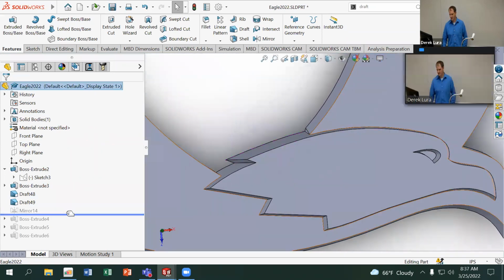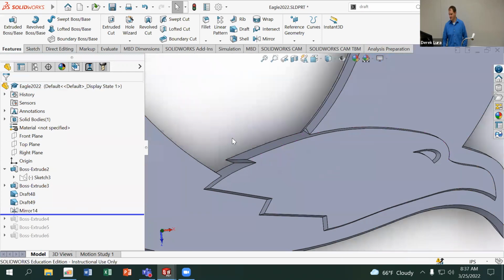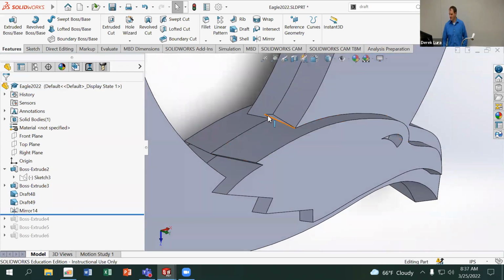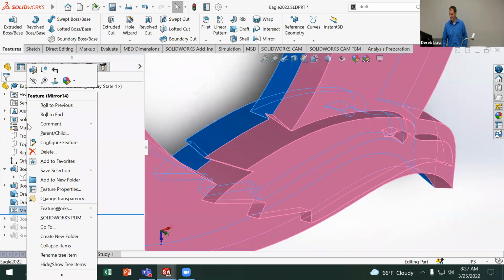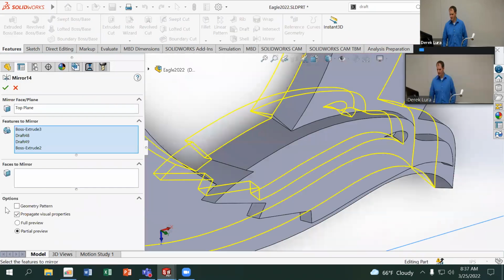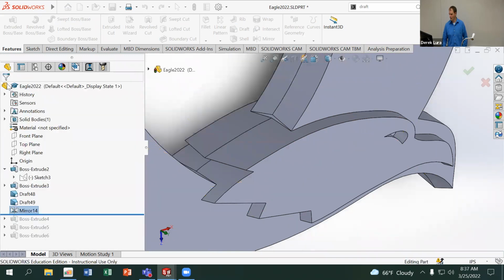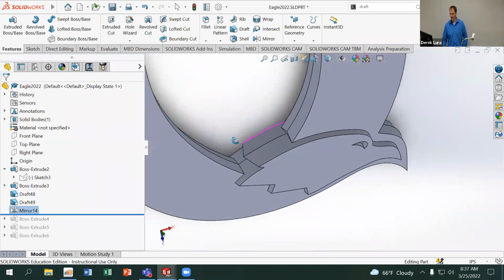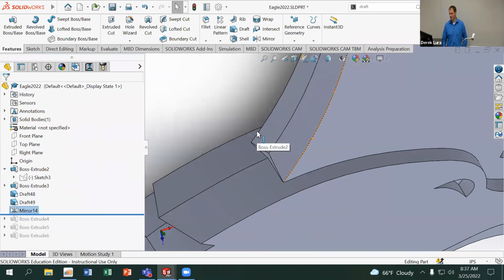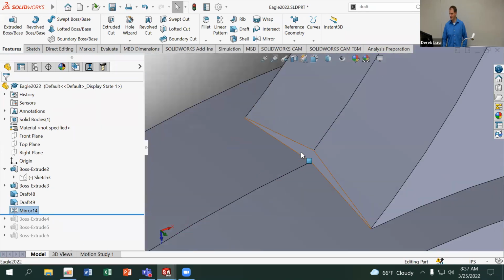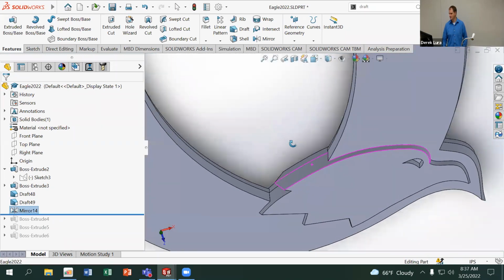And then I just mirrored it about its backside. Look at the opposite side. I'm going to try changing that to maybe a geometry pattern, because you can see that's what I want it to look like on the other side. Yeah. So I just moved that from being a feature pattern to a geometry pattern because the draft was messing up this center face there. That looks better.